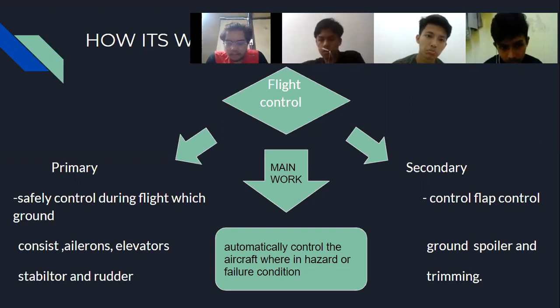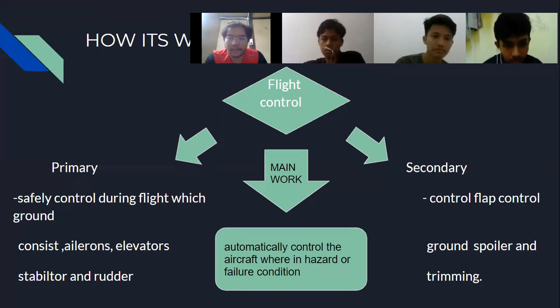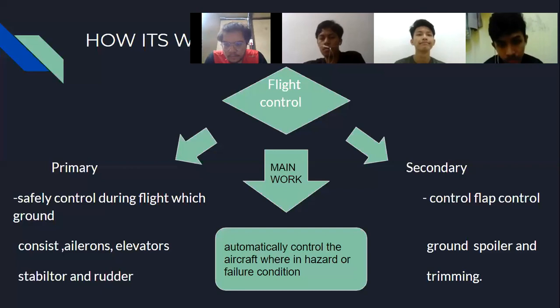I will add some information about autopilot work. Autopilot requires input information to control an aircraft's motion. It is true that when the autopilot is activated, it will go through the path that has been set up. However, the presence of wind can change the direction of flight while it is flying. Hence, gyros, which are used to sense motion, while an altimeter senses altitude, will stabilize the aircraft.